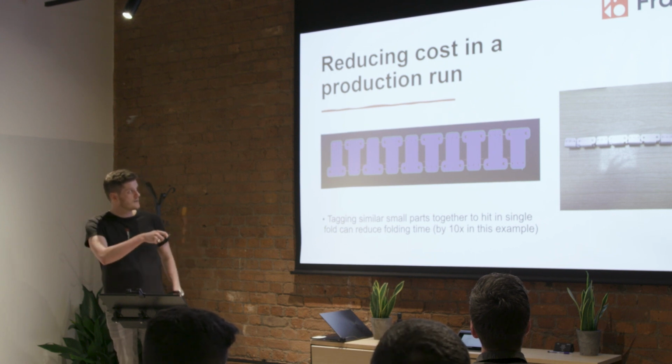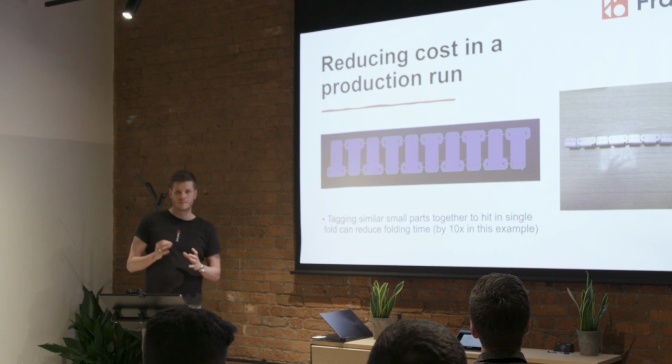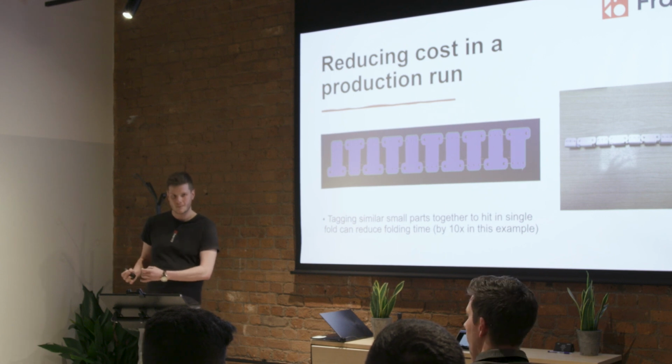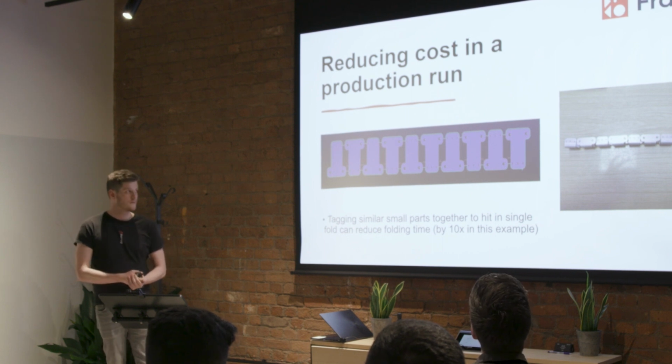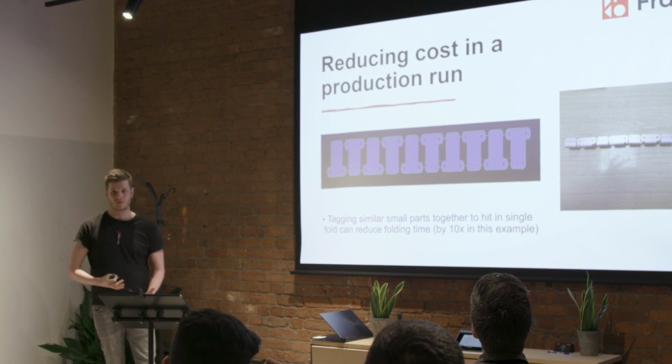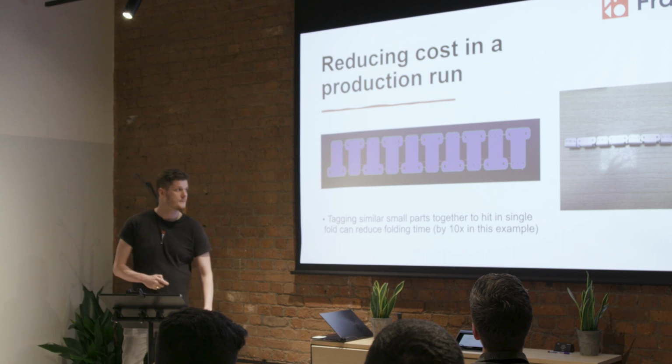But what's usually left behind is a little bit of metal in here and here on the piece, a little pip. For these pieces, it was about 1 to 1.5 mil, depending upon the piece, that was left behind. As it was internal components, it didn't matter too much. For external components or aesthetic, it might matter. But again, talk to your manufacturer about ideas to be able to reduce folding. But if we were to start removing those pips, you'd probably be spending the money that you just saved in doing the folding. So it isn't for every application, but it is definitely one to consider.